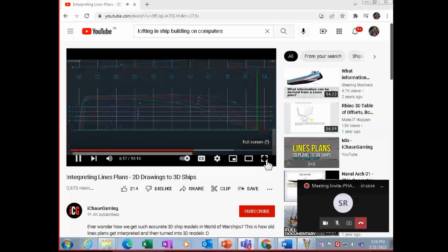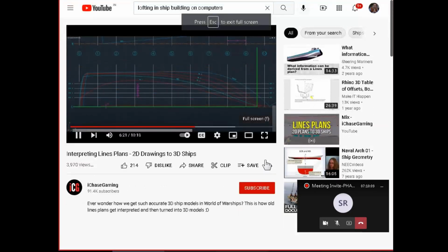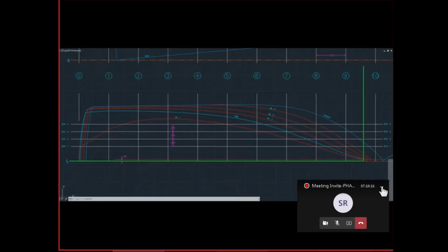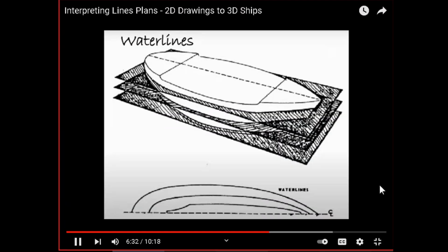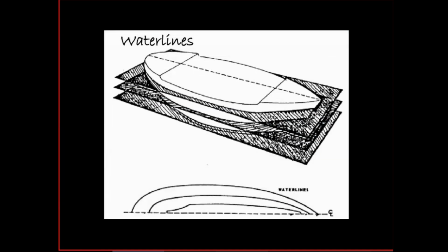And the water plane coefficient, along with a bunch of other coefficients like the block coefficient, would allow me to have a pretty good estimate with regards to things like the powering requirement or the resistance of the vessel. And to help you visualize what those water lines are, here's another picture. So the water lines are essentially cut horizontally across the hull, and you're getting individual slices of the ship from top to bottom.